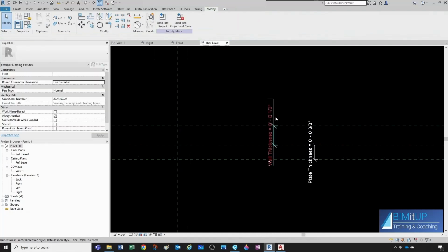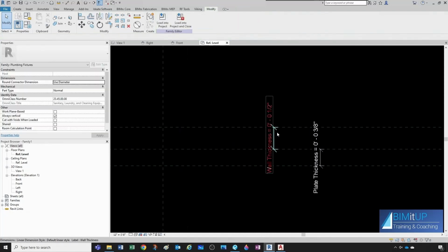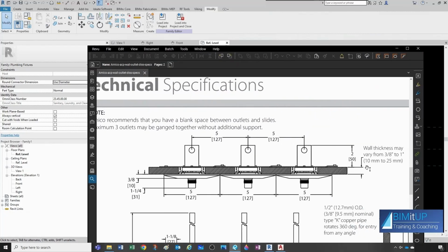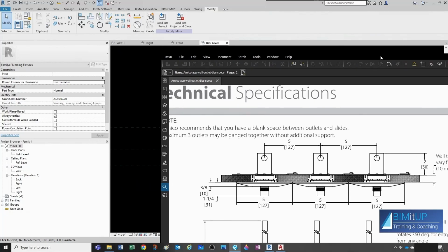And now, for now we can keep it as 1/2 inch, but now it's very nice because we can flex, if we wanted to, between 3/8 of an inch and 1 inch, which is what the cut sheet says. So let's keep going. Now we have to extrude to the back 2 inches to the back of this little drum here. So let's do that.